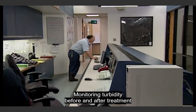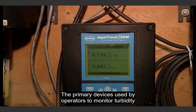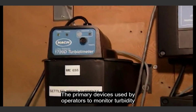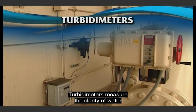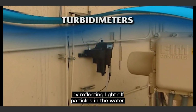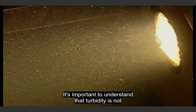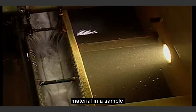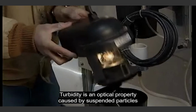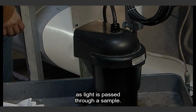Monitoring turbidity before and after treatment gives an indication of how well the treatment processes are working. The primary devices used by operators to monitor turbidity are turbidimeters and particle counters. Turbidimeters measure the clarity of water by reflecting light off particles in the water. It's important to understand that turbidity is not the same as suspended solids, which is a measurement of the weight of suspended material in a sample. Turbidity is an optical property caused by suspended particles as light is passed through a sample.